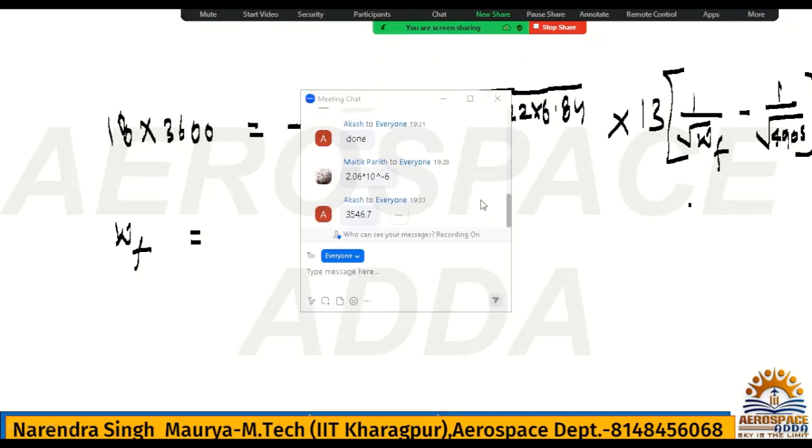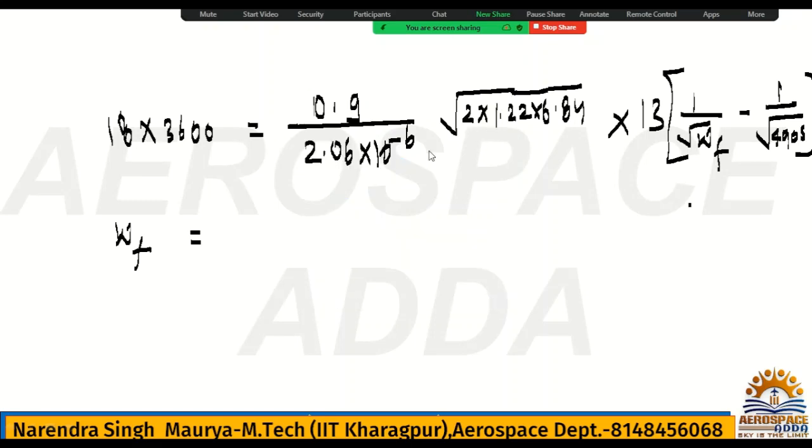Calculation. How much, Matic? Akash, what value are you getting? You understood? Propeller efficiency they have given, eta PR 0.9, so just multiply by it. In your answer it will not give much difference because it's nearby 1 only, but if you multiply, you may get a little variation. In actual you have to multiply because propeller efficiency is given. Tell me dear, what is the value of WF?